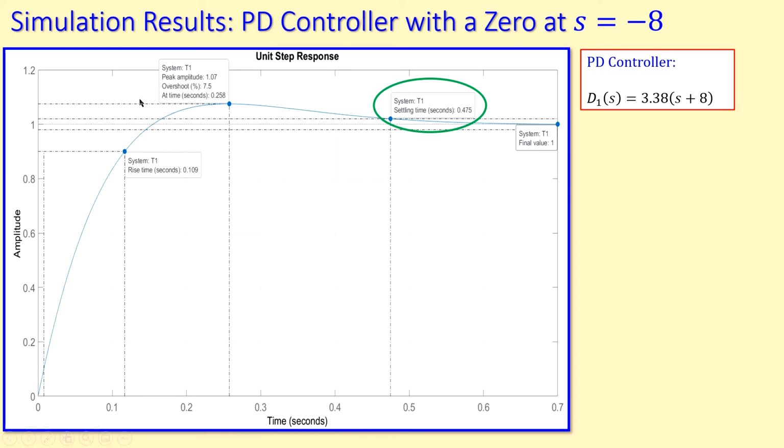That means I have to adjust this again according to the specifications. This is good for settling time, but my overshoot is much larger. So placing the 0 farther away from the vertical axis will only create a larger overshoot. Maybe you can have your settling time smaller, but you will of course create a larger overshoot.